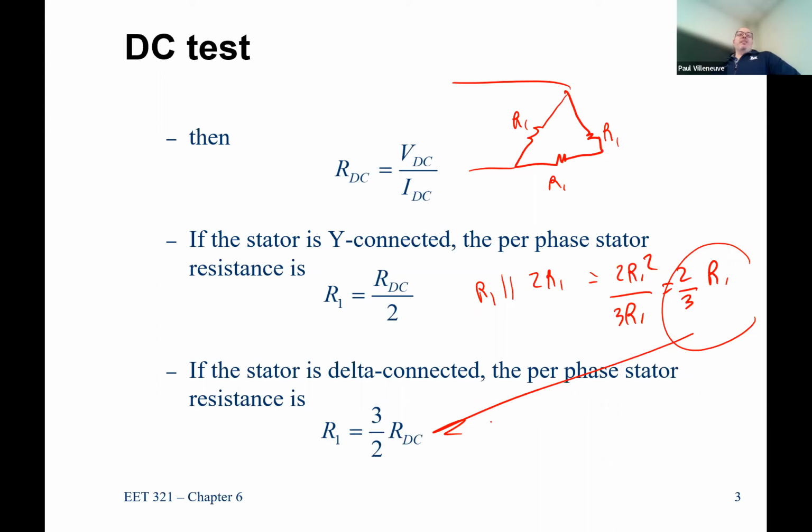The factory acceptance test might define what you want for resistances and efficiencies, and you would test all three lead combinations to figure out an average R1 resistance. So if you wanted higher levels of precision, you would check all the values of R1, and then you just take the average, essentially, just like we did for the transformer.